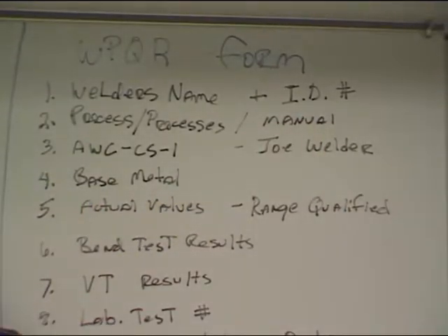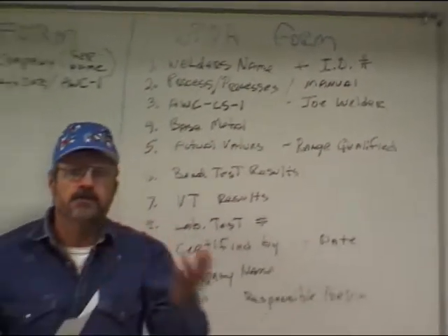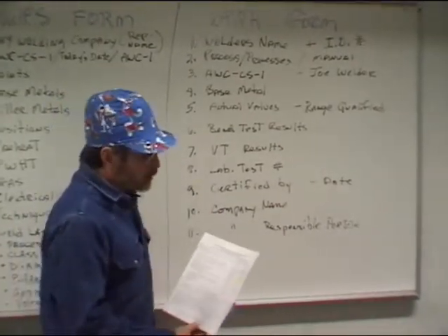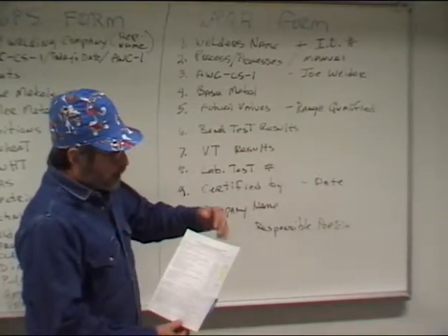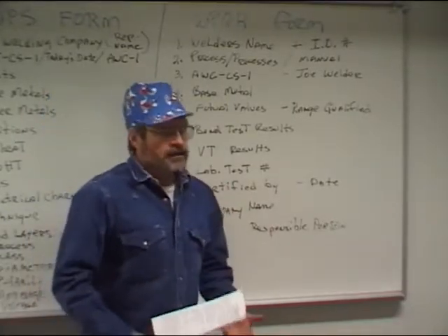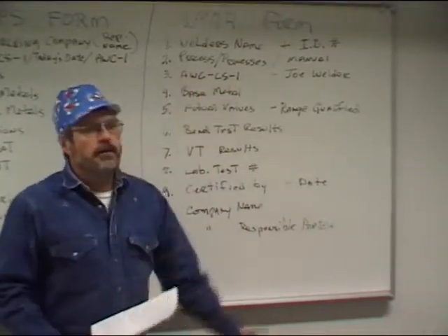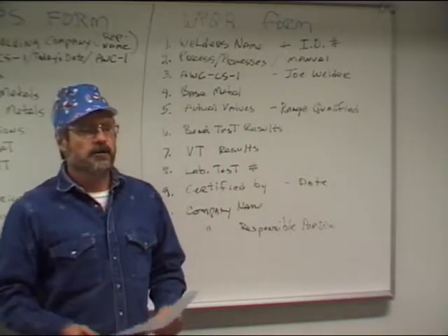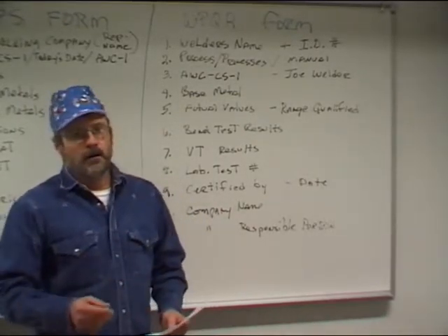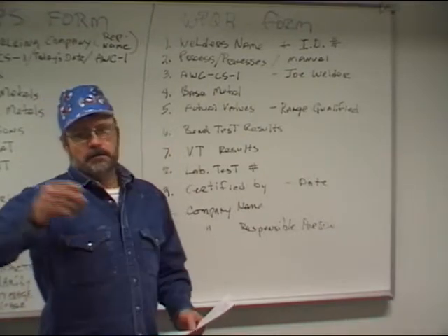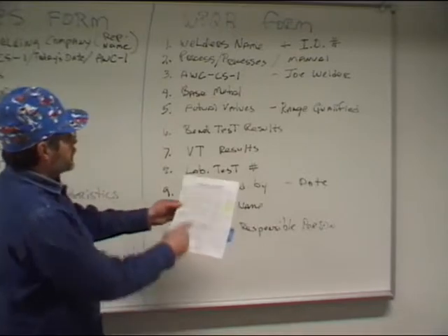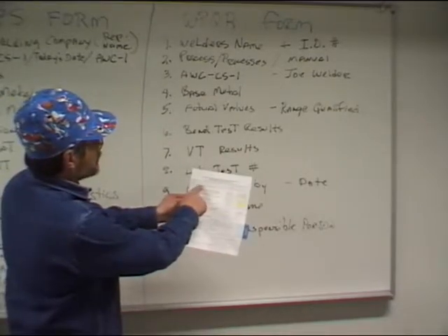Usually what I'll do is I'll use the last 4 digits of a person's social security number. If I'm doing a test for a person, that's what I'll do. Out on the job, if you're over a bunch of guys, it's very typical to just use a person's initials. Sometimes initials are duplicated, and so you might go AA1 or John Collins 2 or whatever it is, and change it like that. And then you're going to put down here welding process or processes used.